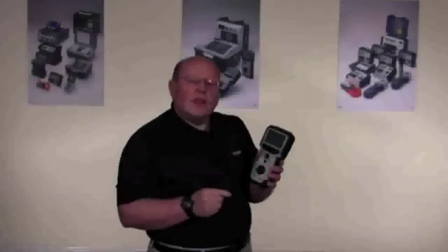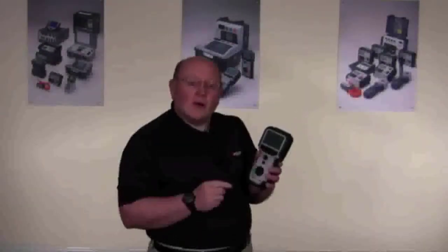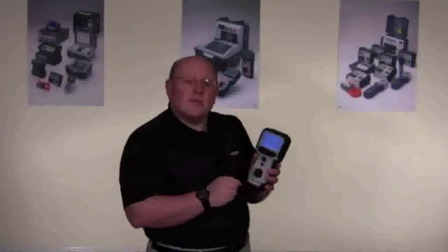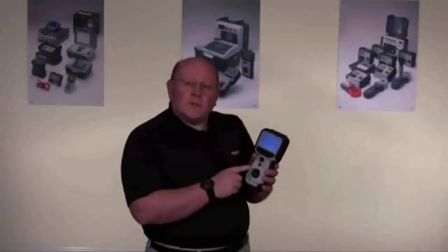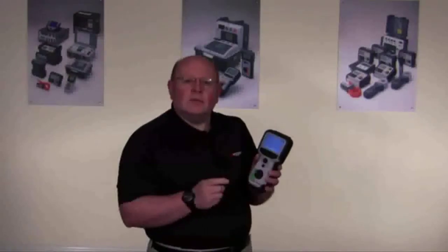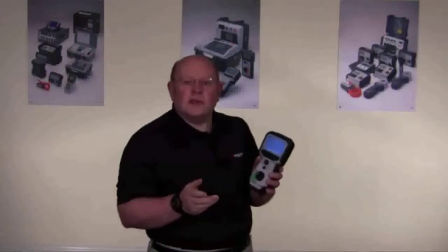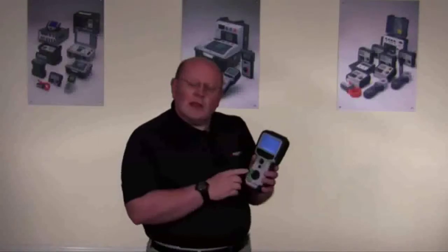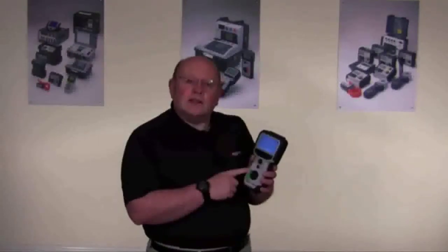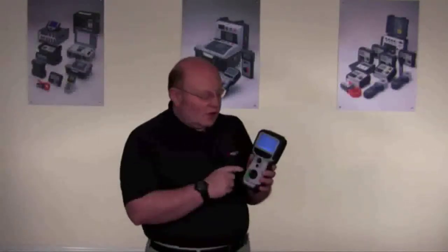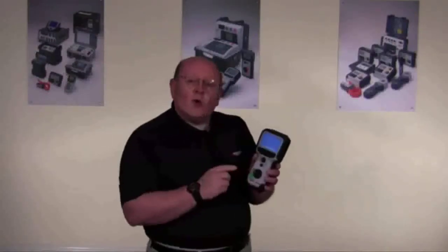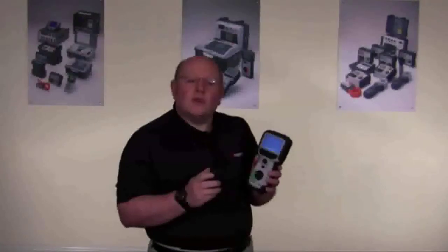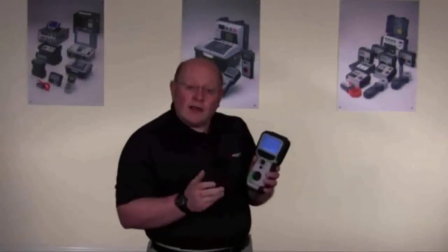The automatic feature on the TDR1000-3 has a number of features. Firstly, we automatically set the impedance on the cable as long as the cable's more than a few meters long. In this case, you don't need to read the specification on the product. You do need to know the velocity factor. Auto also sets up the pulse width to give you the ideal for the range that you've selected.